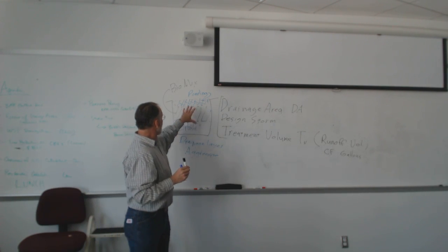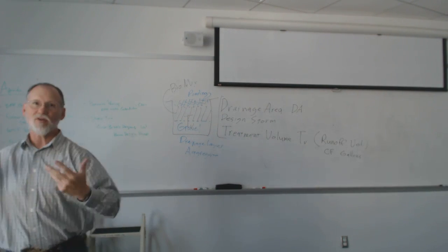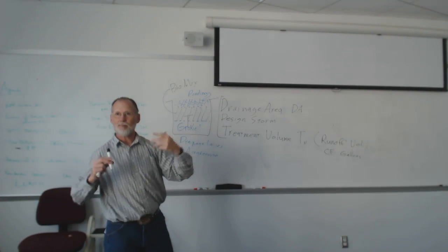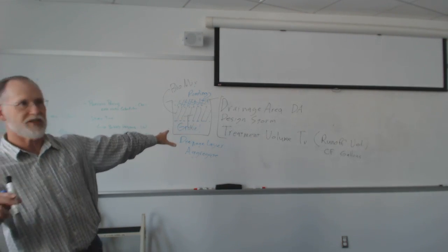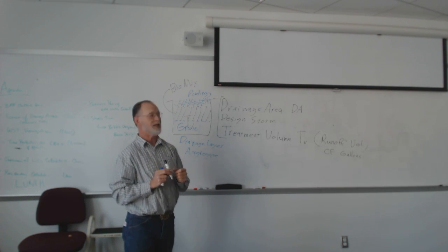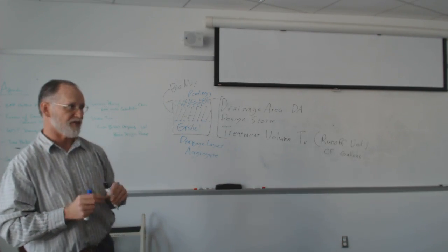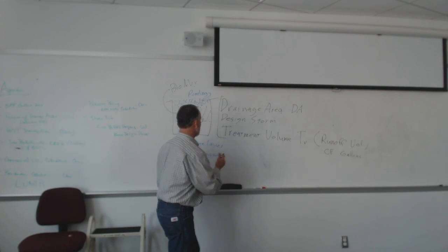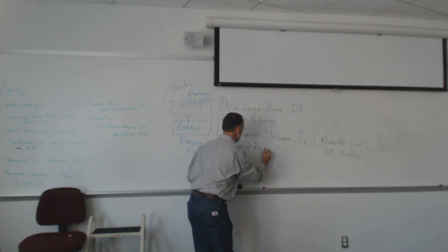So when water flows into this, figuring out how much volume we can have is going to depend on a few things. Gravel takes up space, right? All that bioretention mix takes up space in this hole. You don't just size a hole based on how much water you need, because you've got to figure in the amounts that you have of these various mixes. And to do that, there are commonly accepted void ratios. You can tell the engineer's got a hold of that one.